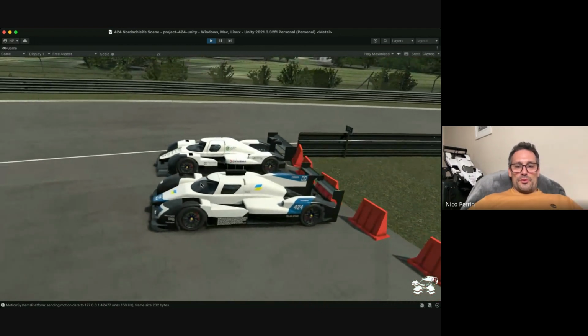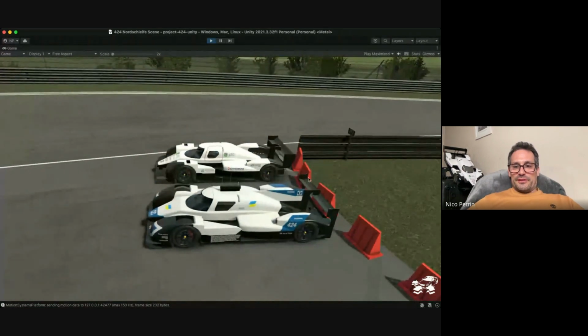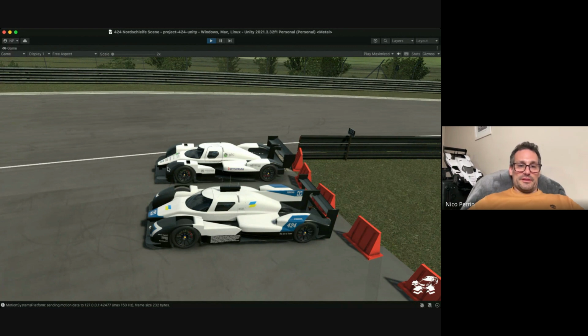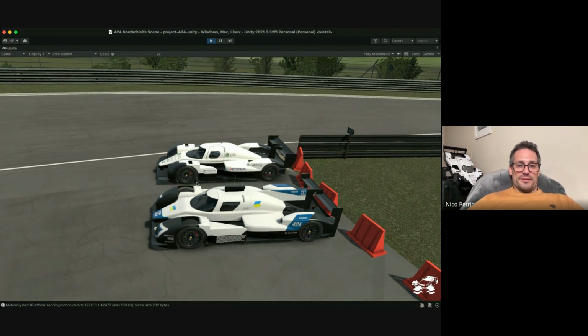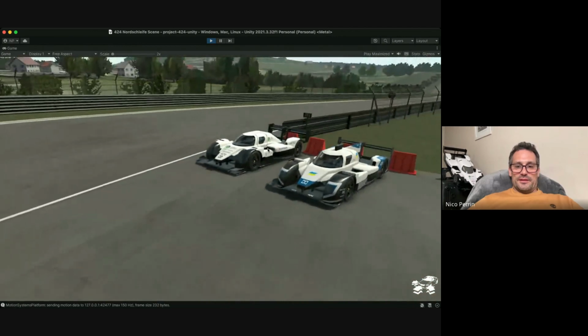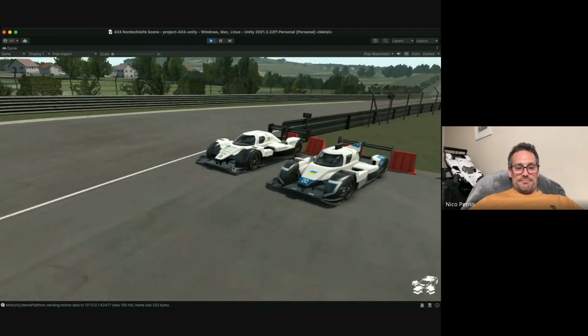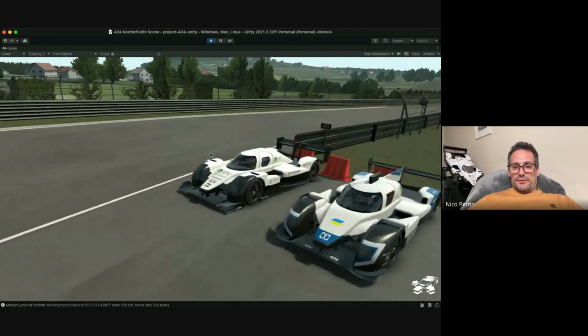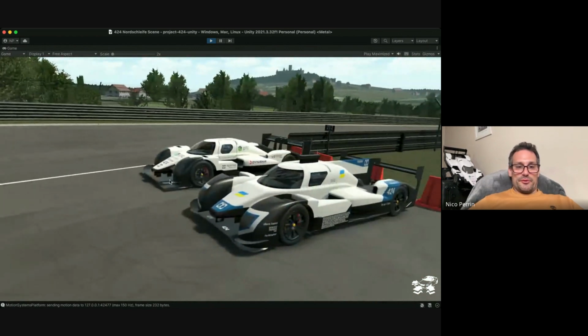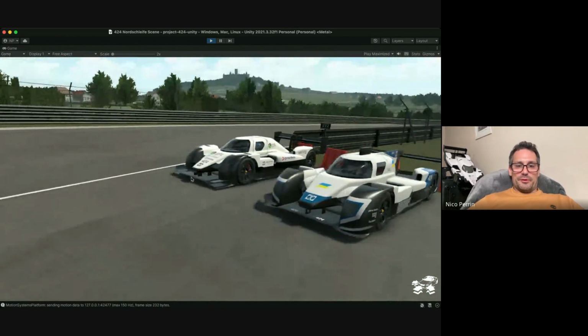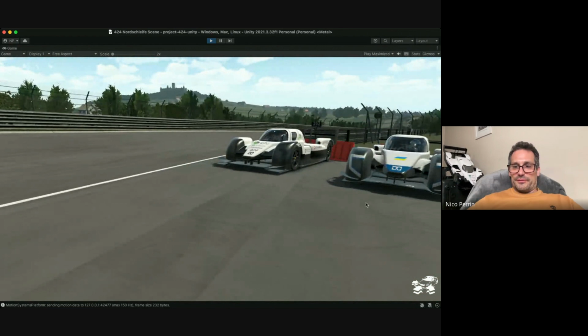To go from a low drag car to a higher drag car, it's not only the wings. Obviously, the rear wing here is much bigger, as you can see. That is a big part of the equation. To rebalance, we needed a bigger front wing. So if you look at the size of the front wing, it has actually been increased towards the front, but also the flap is more aggressive.